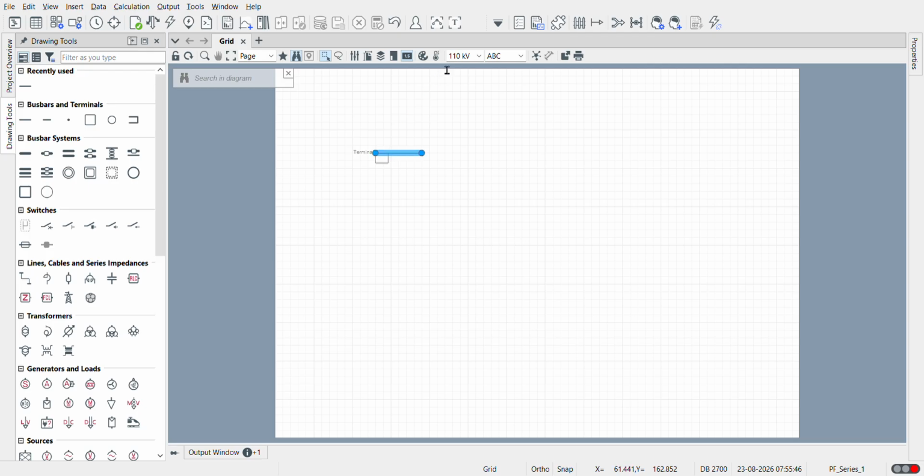Double click it. We need them as buses, because then we will know from which bus to which bus the transmission line connections go, and it will be easy. So for simplicity, let's name this Bus 1. Then we know it is an AC bus, the phases are ABC, and it is a busbar. We have to enter the line to line voltage. For now, I'm using 11 kV.